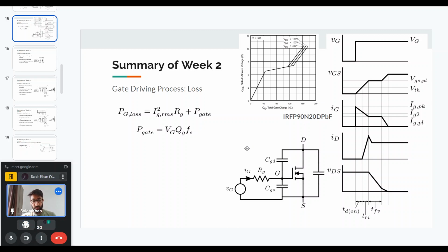Okay, so the optocoupler can have many applications. Basically, if you want isolation for low voltages, then you can use the optocoupler. It can have many applications, and that depends on what you're trying to do. But here we are using the optocoupler for gate driving purposes. And the application of gate driving is just to drive the different MOSFETs and IGBTs that we require.